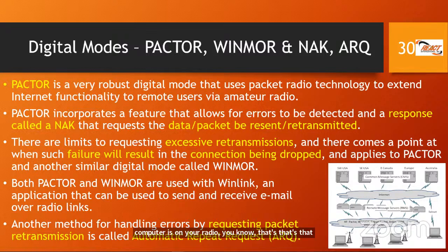Or you can have a standalone connected computer with the signal lines for computer control as well as audio back and forth. One of the modes is called Pactor. When we are communicating, there is a feature called a NAK response. NAK stands for negative acknowledgement, and it means that you are requesting that the packet or the data be retransmitted. That will be an exam question. It's saying, please resend that bit of information, because maybe the computer didn't get it or it was corrupted.